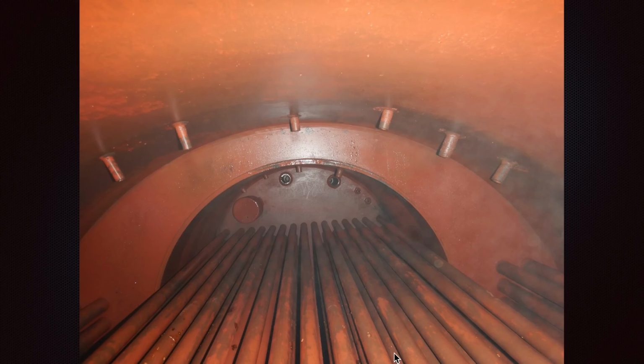Here there is steam generation on the top. The boiler water level is about here, as we can see, and here already the steam goes to the steam outlet. This is the main steam outlet valve of the composite boiler. So here, as you can see, the steam flows, hits one plate there, and whatever water is accumulated is dropped back from this opening down again.